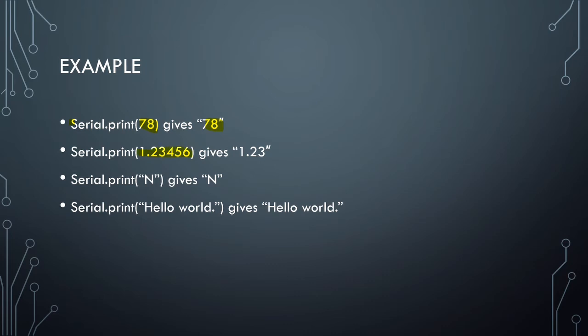It's important to note that if you don't specify otherwise, serial printing will typically only reference 2 decimal places. So if we really need to, we can change that. Typically, this is all that's needed. This is all we'll need for this course. But just note if you need more than 2, that'll take some extra work, because serial print typically only prints out 2 decimal places.